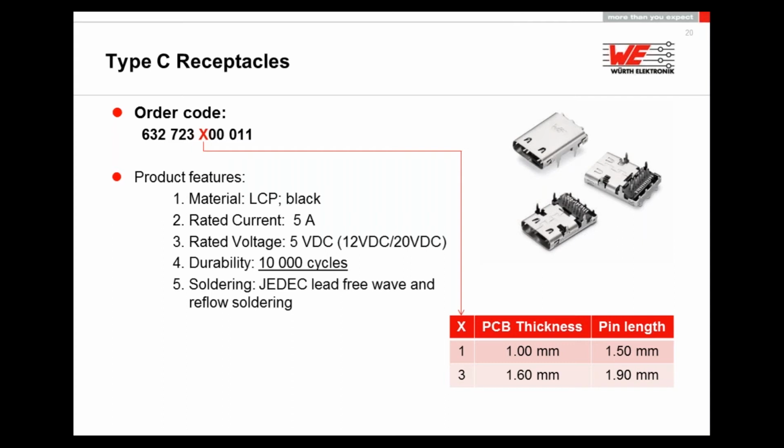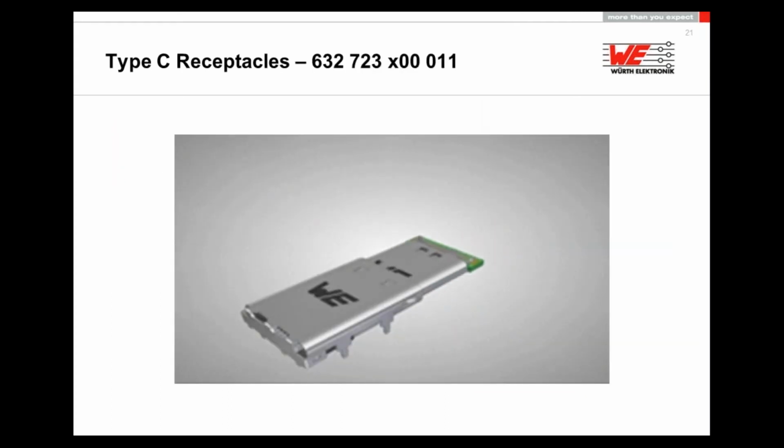Another point we have to keep in mind when we speak about our PCB design is the thickness of the PCB. Well, we know that we are speaking about a high-speed connector that is able to handle really high frequencies, and the frequency signal we are able to handle is also affected by the line impedance, and that means also by the line length.